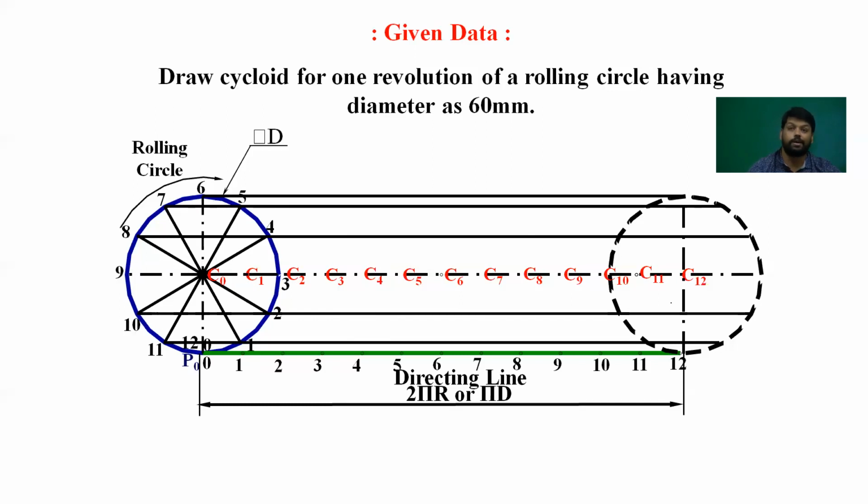Depending upon that you need to take the appropriate decision, because in the problem statement it will be clearly given on which point you need to draw the cycloid. For us, in this simple statement it is not mentioned which point we have to draw the cycloid for. So we are taking the bottommost point, which is in contact with the straight line.